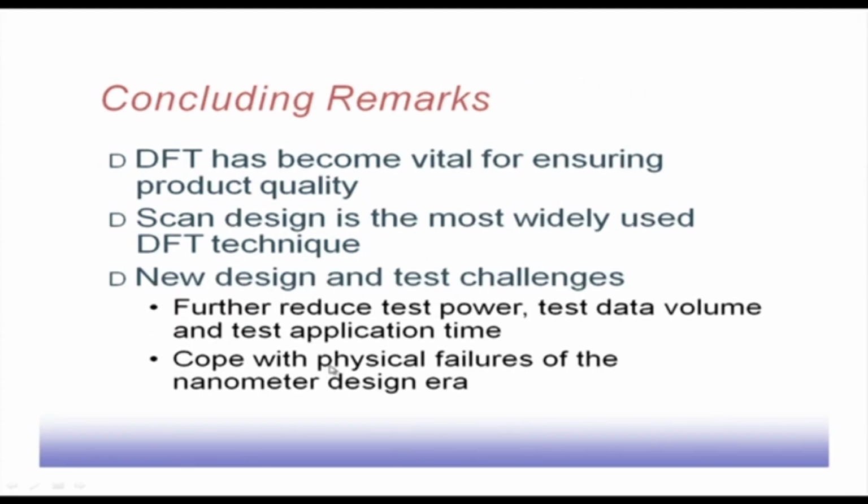So, DFT has become one of the vital tools for ensuring product quality. Scan design is the most widely used DFT technique, because that is now more or less accepted, that these scan chains are to be inserted. So, all these CAD tools that we have are now supporting this DFT insertion technique. There are new design and test challenges coming up for DFT design: reducing test power consumption, test data volume and test application time.